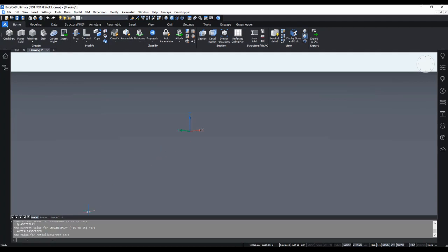One other item is to type in selection modes, and we want that to be set to 6. We're going to talk about this later in more detail, but basically that's referring to some things up here with the prioritization selection for edges, faces, and boundaries. And with 6, we want the edges to be off and the other 2 settings to be on.